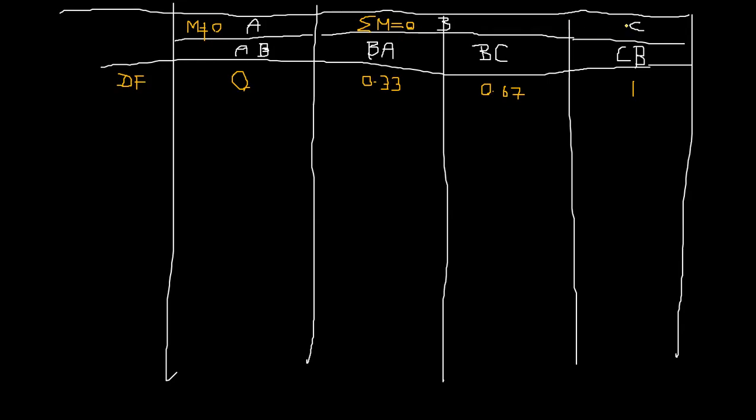Here it's a discontinuous support, so that means it only has one member and that member moment is 0, right? So the final sigma M is the summation of the BC and BA moments, right?